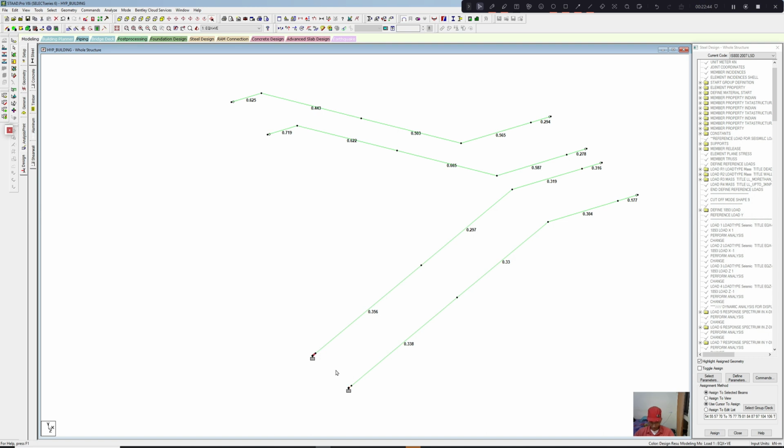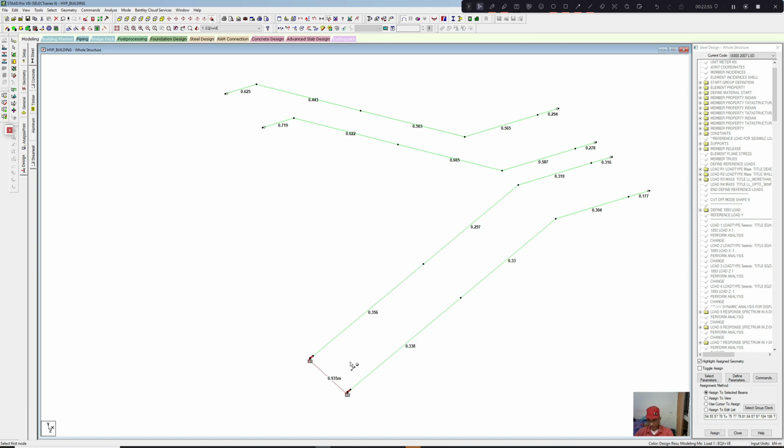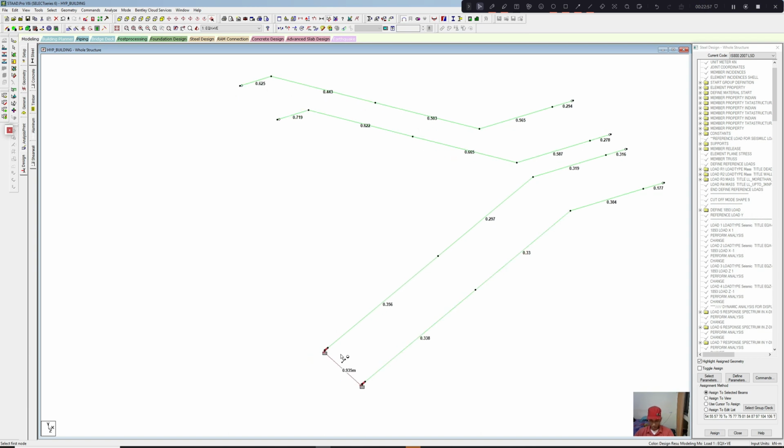So this part we can actually neglect because our actual slab will be up to this point, up to the support point. So we are not taking it to the support point because we do not want the deck slab to transfer lateral load in the model.